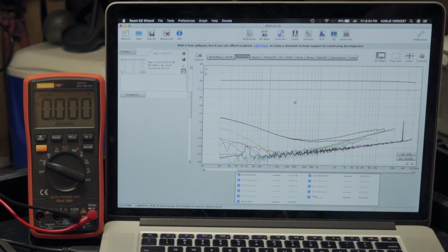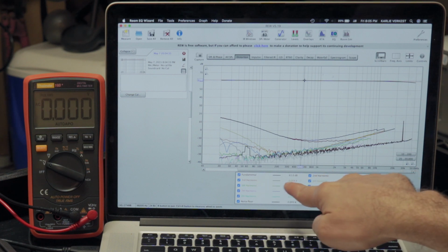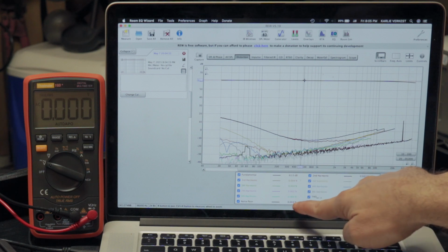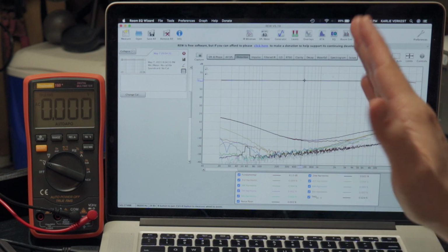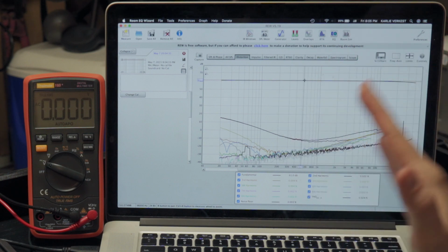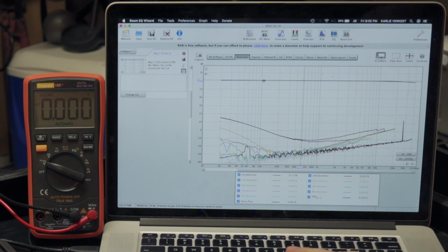So much more data than in the first video, where we were just doing square waves and sine waves, and we had that piddly FFT on the scope itself. But holy cow, look at this. For any frequency that you want to choose now, you can come down here and look at the exact percentage of harmonic distortion and noise at that frequency. It's like we just went through every single frequency and did one of those FFTs to it, right? So we have all of this right here to see.